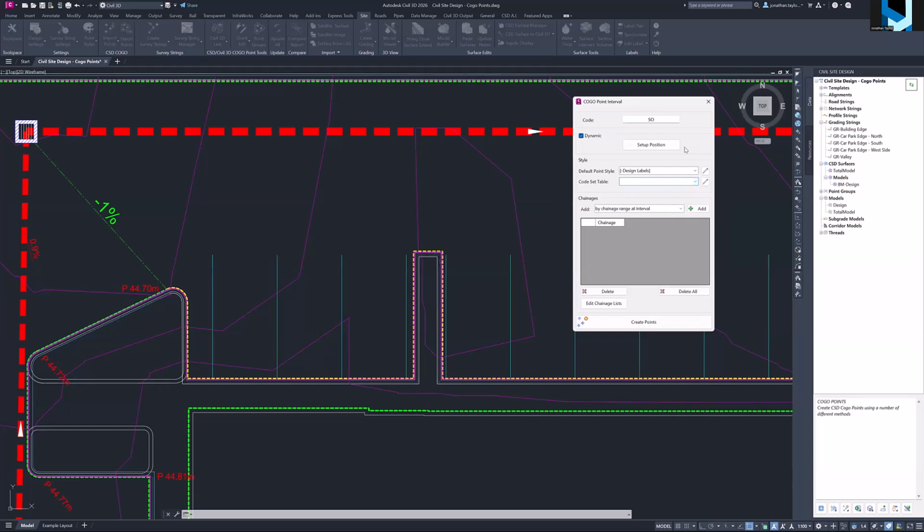I know that's in there, but having tracked through this now for quite a long amount of time, code set tables don't really get involved with any of what we're doing. Then you can say how often you want to Cogo, by chainage, by single chainage, by sections. However, because we've picked the alignment in the horizontal option, if you didn't pick it, you pick polyline, you won't see all this. What I'd like to do is say, look, yeah, I might have the horizontal geometry. So I'm going to go 10 meters horizontal geometry only, but I want to see what that looks like.